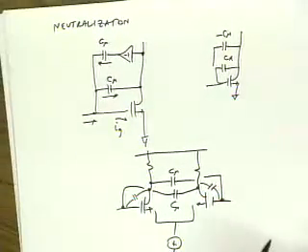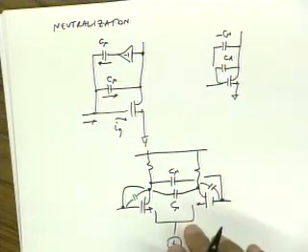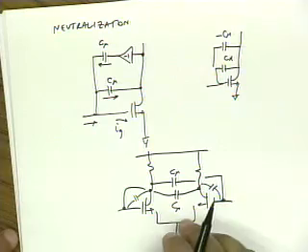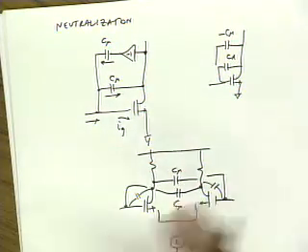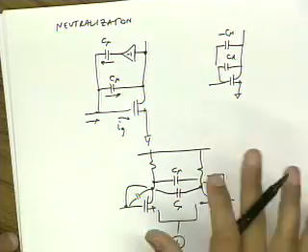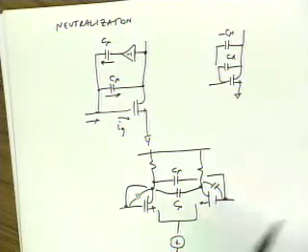All right, any questions? Does that make sense to everybody? And there's other ways to do it. We won't go into details. You can use transformers to provide phase inversion, for instance. You could use center-tapped inductors. So there's lots of tricks that you can play.